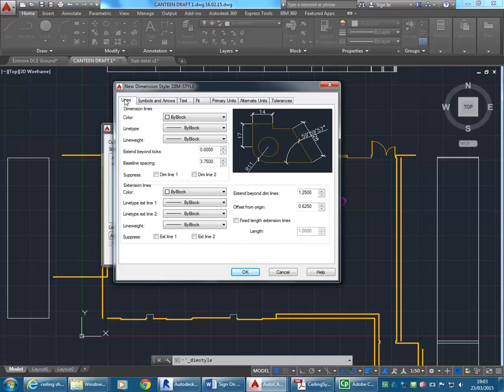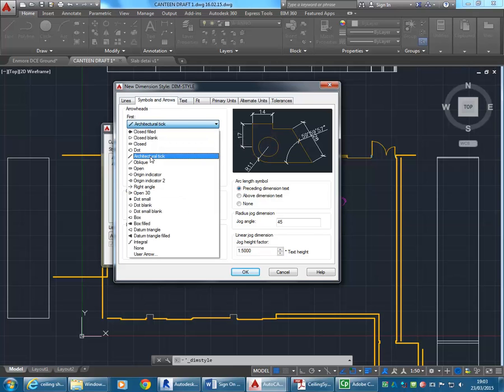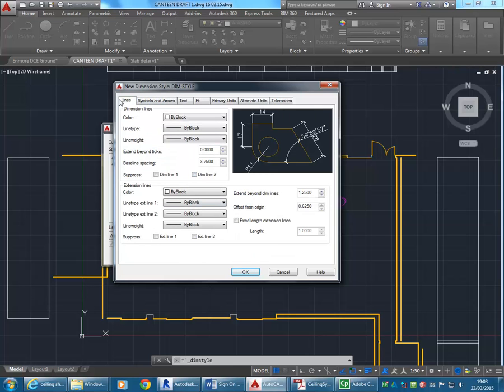And so when I go to the Lines tab now, this is all millimetres. And the reason I do it right to left is because you need to have options here, like architectural tick, to get the options on the first panel, on the Lines panel, to come up. So now I'm going to set the extend beyond ticks there to, I'll just set it to 2 so you can see what it's going to do. Okay, so if it wasn't clear, it's added these little extensions on the end of this line.